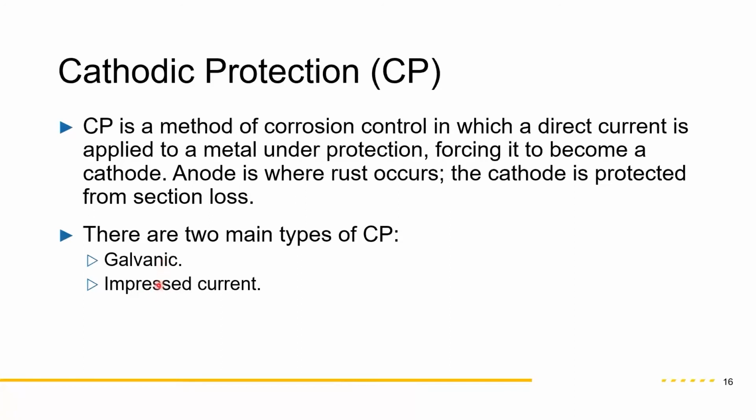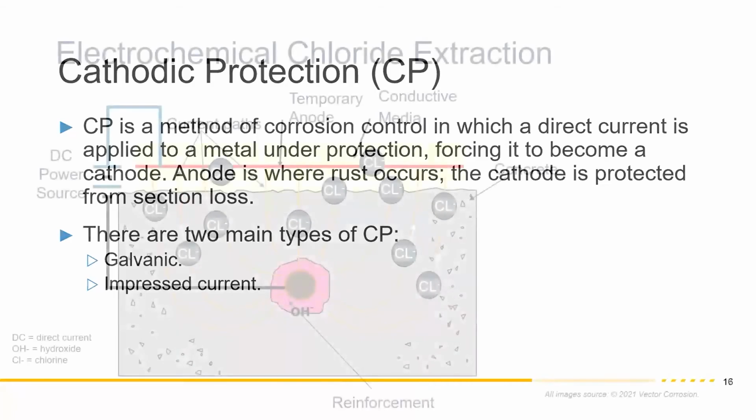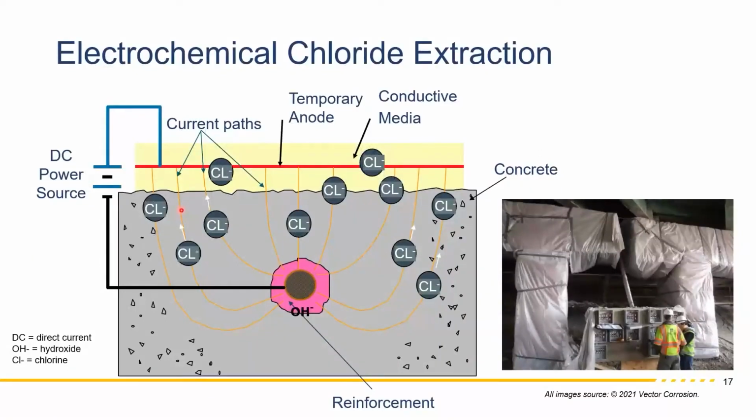You put a sacrificial element on the pier itself, so that would preferentially corrode. This is very important protection, especially in a marine environment, aggressive environments. Especially say down there in Boston, that might be an option to stop the corrosion from occurring any further.